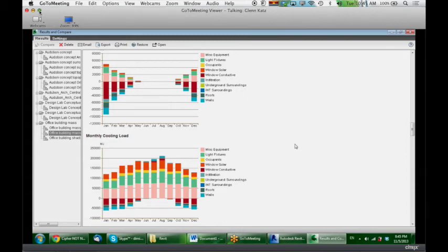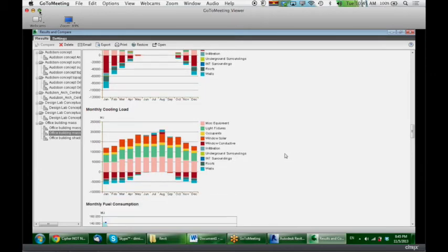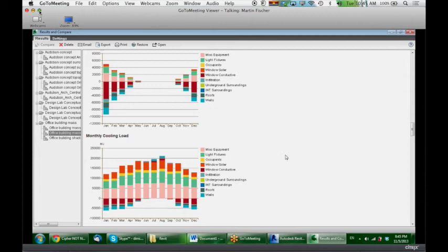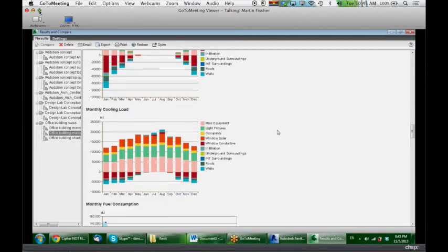In the conceptual model, what can we change that would bring the window solar load down a little bit? Shading. Okay, so the amount of shading on the windows? Yes, that would be, let's say, the cheapest and most immediate solution that should come up. We can also look into different window types and everything, but that's more expensive. But shading will do a pretty good job as a first strategy.